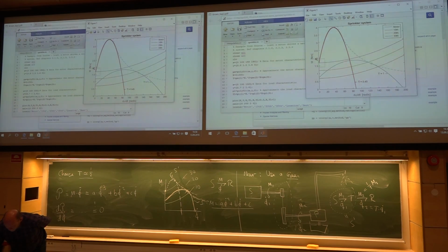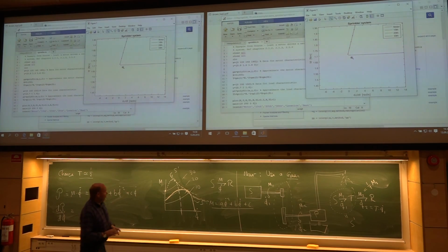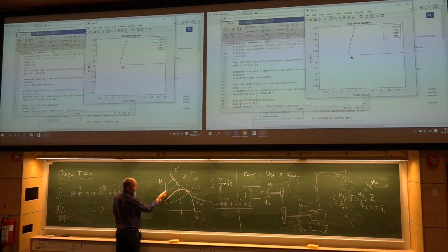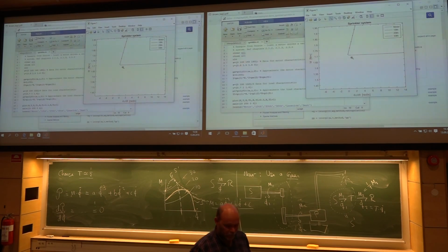you should see, yes, you just make it, because if the load were to be higher than the actual torque you have on the motor, it will never start rotating. The pump will never start to run, and the motor probably will burn up. So I would say not 1/2 but 0.45.